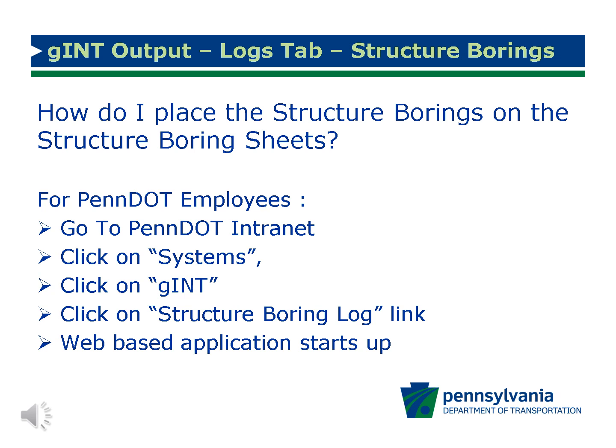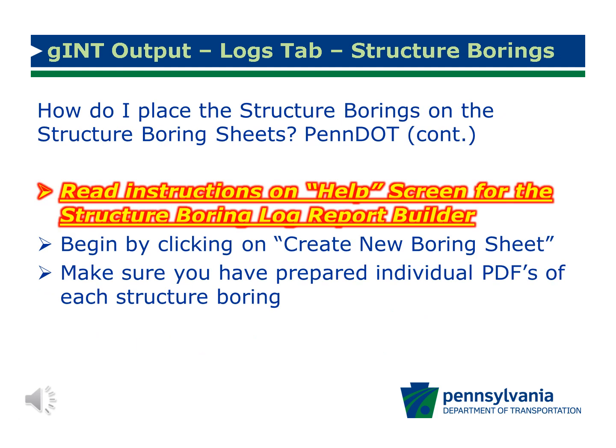PennDOT users will be asked to browse for PDF files, the boring location plan, structure borings, and lab test summaries. The application will automatically place the PDF files on the structure boring sheets. When using the Structure Boring Log Report Builder on the intranet, please read the instructions on the help screen before entering data. After opening the Structure Boring Log Report Builder, begin data entry by clicking on Create a New Boring Sheet.